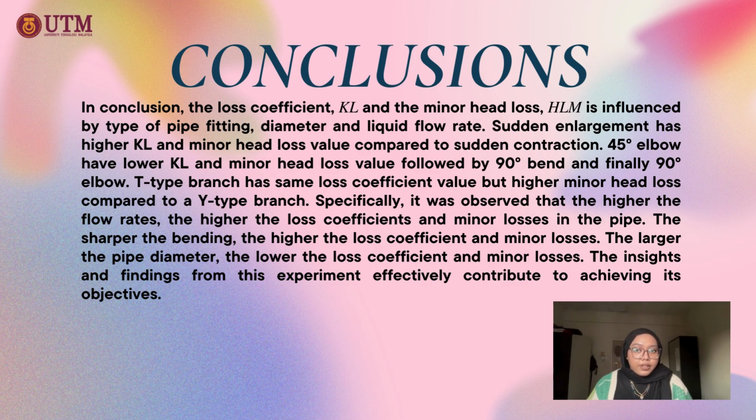Specifically, it was observed that the higher the flow rates, the higher the loss coefficient and the minor losses. The second thing that we came up with is the larger the pipe diameter, the lower the loss coefficient and minor losses inside of the pipe. And then the higher the angle of bending, the higher the loss coefficient and the minor losses. These insights and findings from the experiment effectively contribute to achieving our objective.